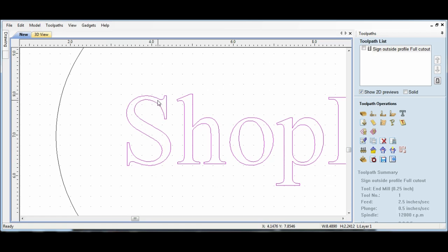So it's going to do an invisible line down the center, and it's going to start here, and it's going to raise the bit, the little V bit we're going to use, until the two edges of the V bit are touching the two edges of the letter here. But then as we go out here, it gets wider, so it's going to plunge down until the two edges are touching the two edges of the letter, so on and so forth, where you get that thin and thick lettering.